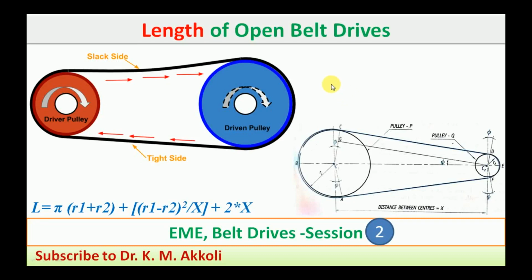Hello everyone, welcome back. Next session of the belt drive. In this one I am going to take the length of the open belt drive. What is meant by the length of the open belt? It's the total length of the belt which is wrapped on the two pulleys for the power transmission.